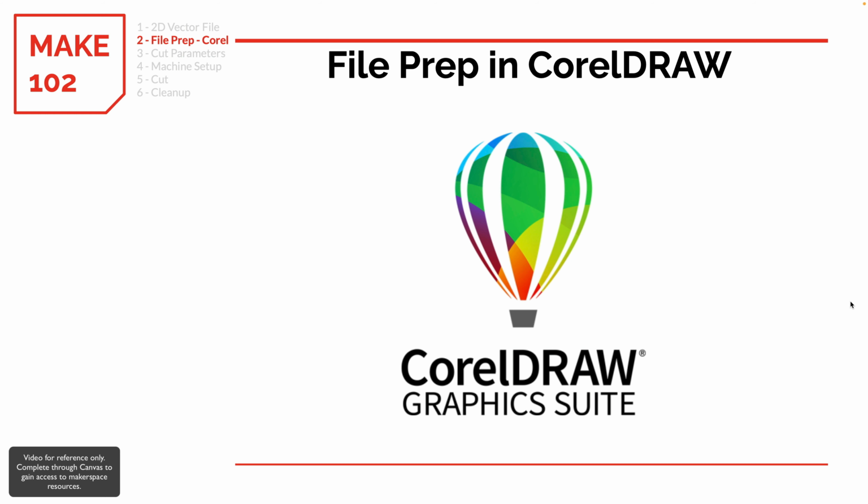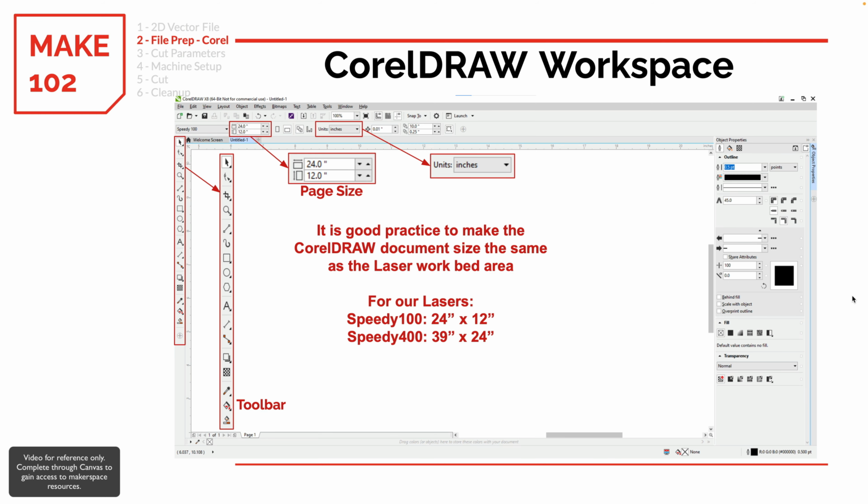So let's first take a look at how we would prepare our files in CorelDRAW. First, we would start CorelDRAW and open up the files. And then we would want to look at a few things around the window. So we want to make sure that our work size is correct for the laser that we are working for. So if you're on the Speedy 100, you want the work size to be 24 by 12. And if you're on the Speedy 400, you want it to be 39 by 24.